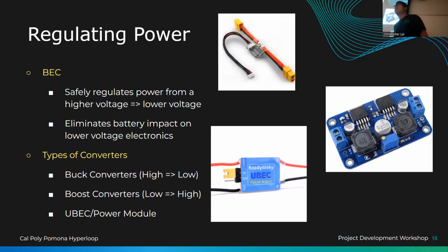Now the next slide is really important, because now that we talked about LiPo batteries, you might be really interested in taking this and just connecting it to a robot or an Arduino. And let me tell you, if you connect this to an Arduino, the Arduino will explode. It's happened to me before. Don't try it. Arduinos usually can't take in a high amount of voltage, as you can see in one of these batteries. This is a 3S, so the maximum voltage is 12.6.